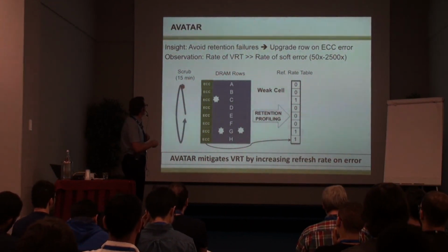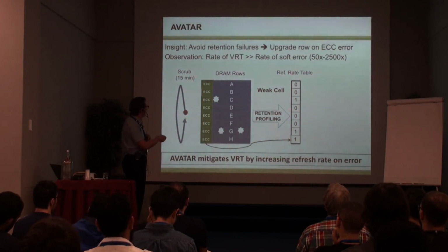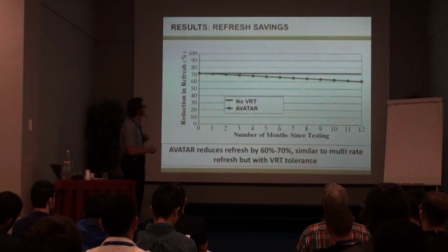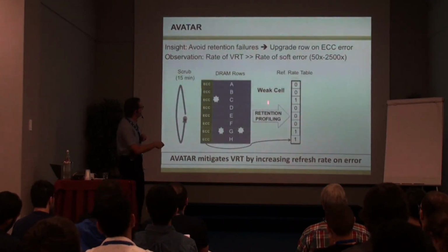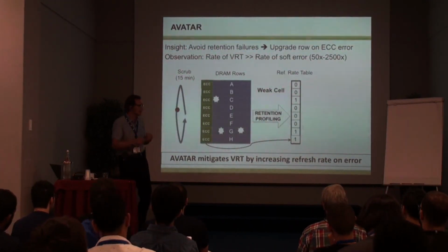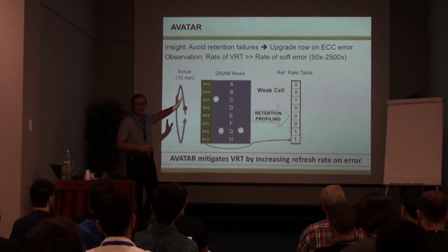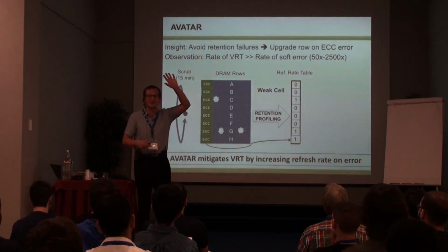And you can actually figure out whether you get errors at low refresh intervals, and based on that, you can upgrade the refresh interval of the cells accordingly. I'm going through this relatively fast, but it's a very simple idea. If you get an error, increase the refresh interval.